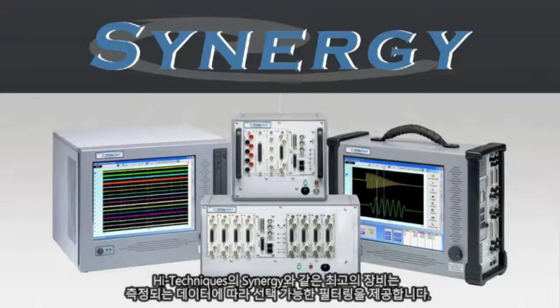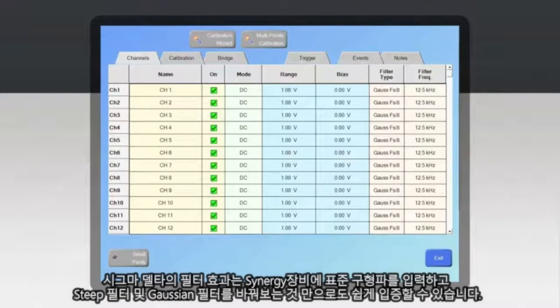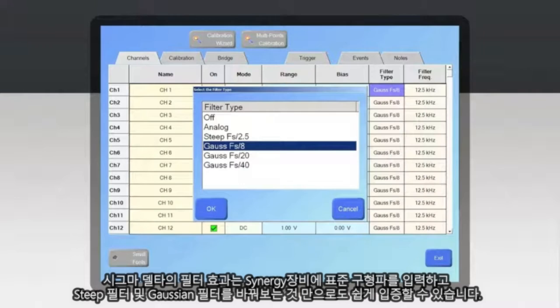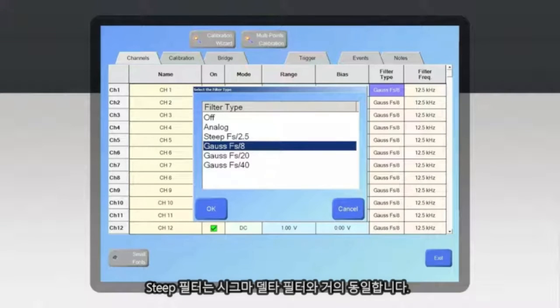The best instruments, such as the Hi-Techniques Synergy, provide selectable filtering depending on the data being measured. The filter effect of the sigma-delta can be easily demonstrated on the Synergy simply by inputting a standard square wave and toggling between steep and Gaussian filters. The steep filter is almost identical to that of a sigma-delta filter.